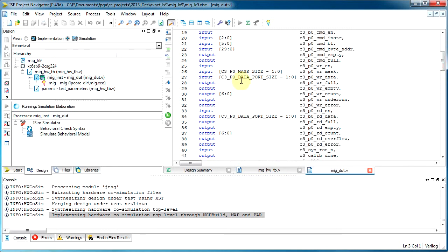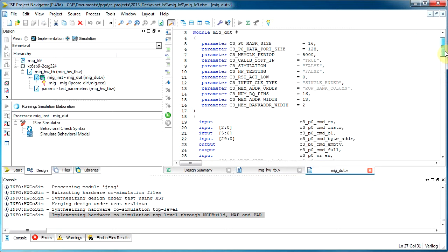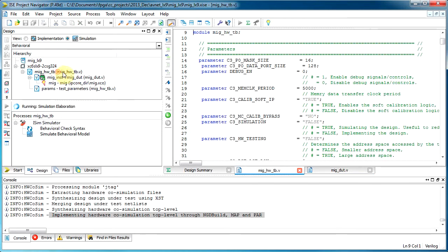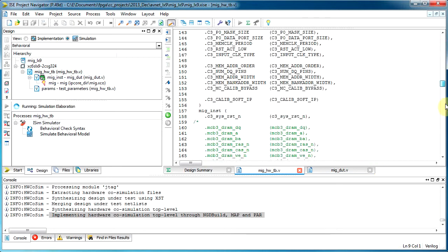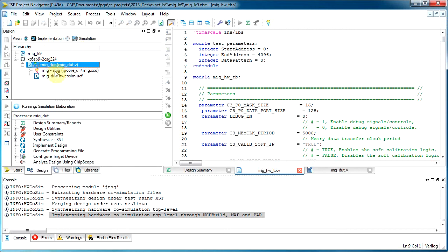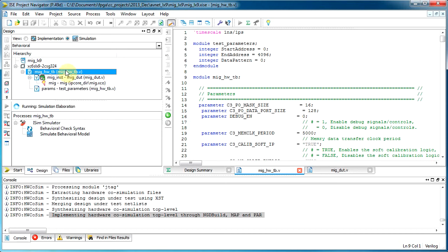You can see all of these large ports are going through the test bench, so it may cough out at some point because it doesn't have enough I/O pins, but often even just running the synthesis will give you an idea what the actual errors are. So I find it a little easier to just pop into this side and run any process you need, rather than finding the actual log files that it's written somewhere when it's implementing for the simulation phase.